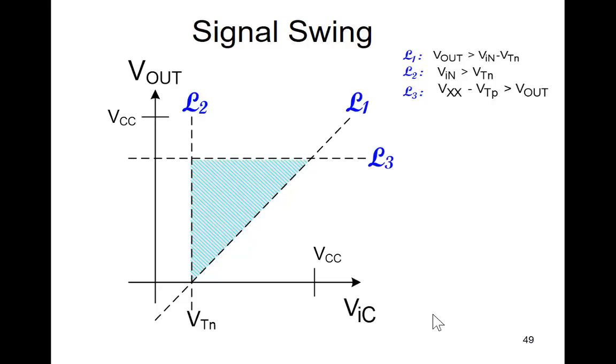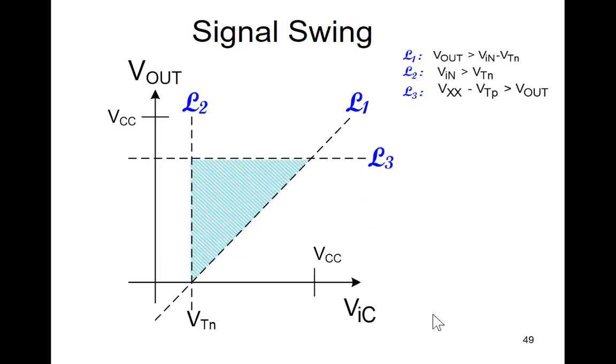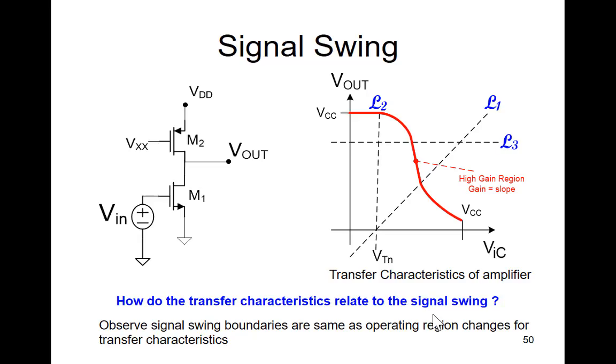That's why we use a tail current to bias, because this has a good common input range with a tail current bias. But on this circuit here, I don't have a tail current bias. I'm looking at a different amplifier right now. Okay? We can come back and do this with the other structures as well. So I'm most interested in the process of how we find signal swing, and I've looked at this structure initially.